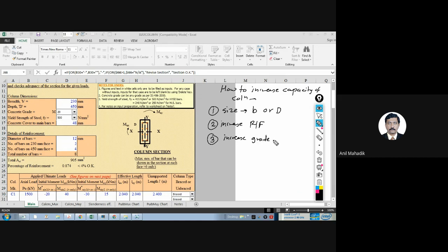So there are a lot of choices. Plasticizers? No, plasticizer, no. There is no other way. It depends only on the grade, either M20, 25, M30, 35, 40. For high-rise buildings, we generally use minimum 40 grade. But if it is a low-rise or mid-rise building, then you can say 25 to 30. High-rise buildings have grades of 40 minimum and higher.